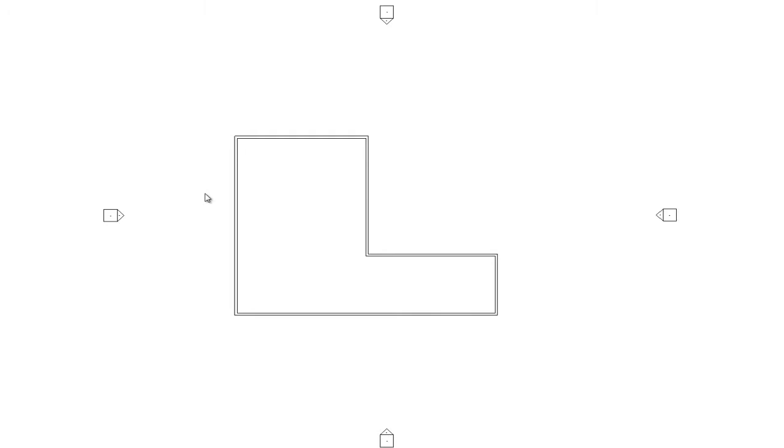Now we'll take a brief look at how we can modify the location of walls once they've been drawn. So when you want to move a wall, you're going to select the wall that you specifically want to move. So we select this wall and we see the temporary dimensions show up. We can simply click on the text for one of the dimensions or the number, and then just type in a new value, say 20, and hit enter. We hit escape to clear that selection.